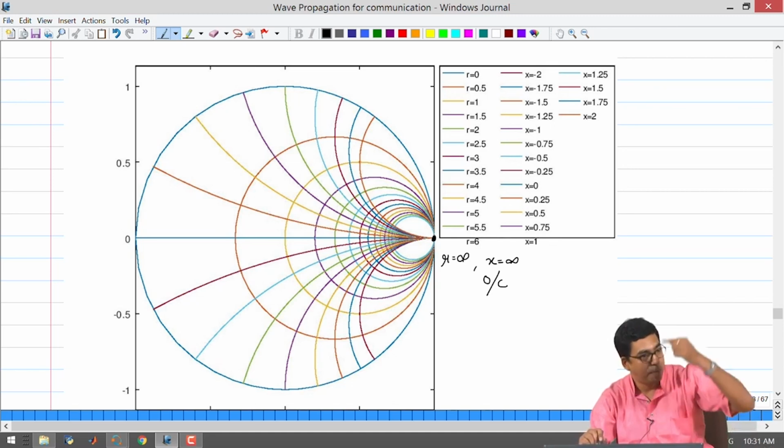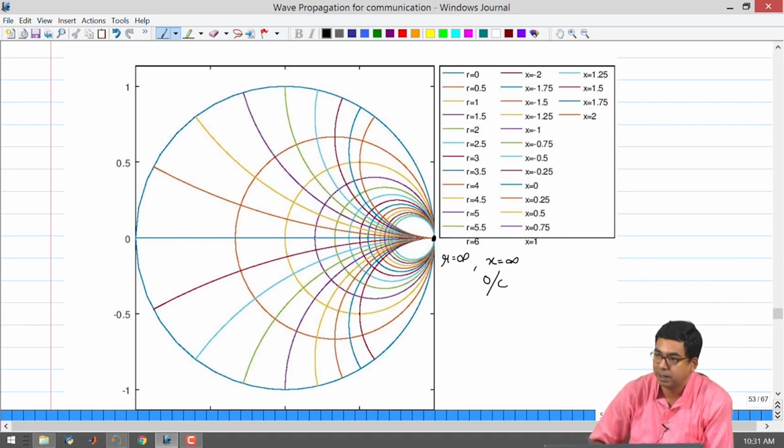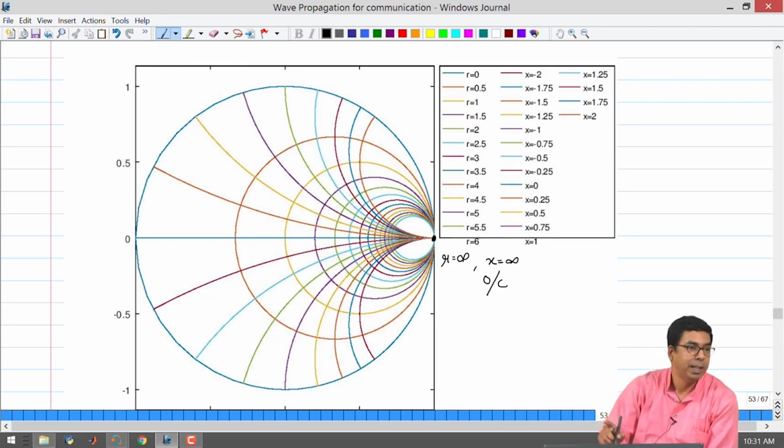So, we can go back to the derivation that we made for the reflection coefficient for an open circuit. We would have got ZL minus Z0 by ZL plus Z0 to be equal to 1. So, the analytical way of finding out the reflection coefficient is by using the formula ZL minus Z0 by ZL plus Z0. The computational way you are already aware, write the telegrapher's equations and try to see what is going back.